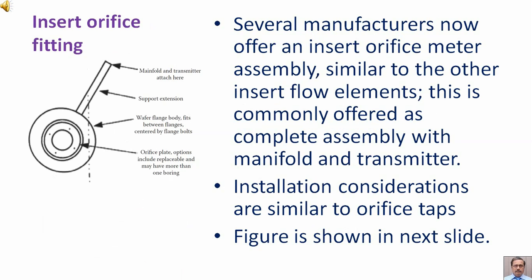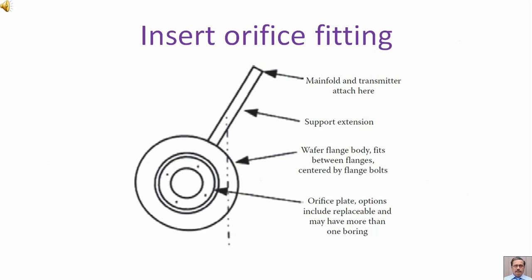Insert orifice fitting. Several manufacturers now offer an insert orifice meter assembly similar to the other insert flow elements. This is commonly offered as a complete assembly with manifold and transmitter. Installation considerations are similar to orifice taps. Figure is shown in next slide. Insert orifice fitting.